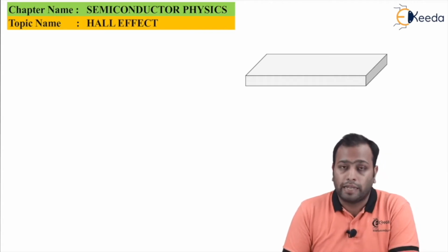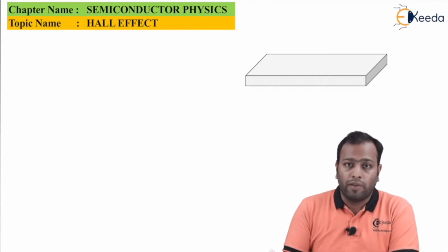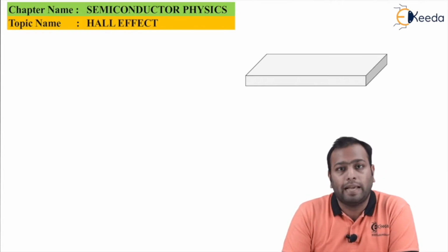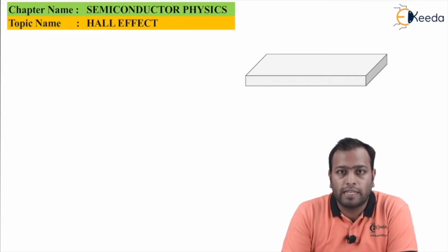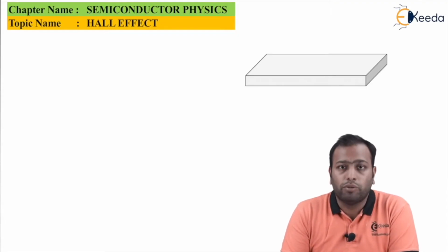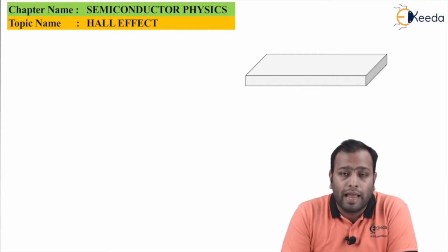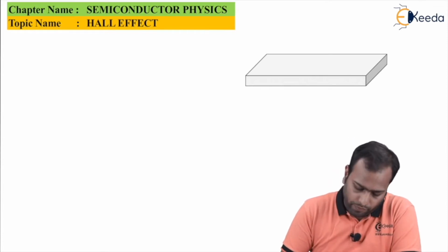This is a metallic conductor which we have assumed. We have now assumed this to be a p-type semiconductor. Well, why did we choose a p-type semiconductor? Well, because it has majority carriers as holes, which are demonstrated as positive charge carriers. You can do the same derivation by using an n-type semiconductor, and of course then replacing holes as the majority carriers with electrons as the majority carriers.